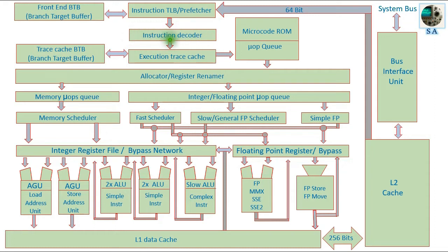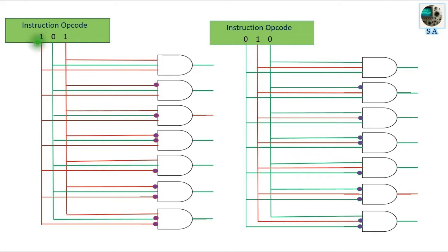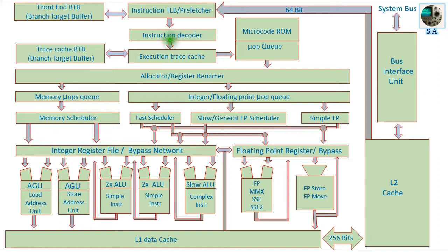The interesting thing about decoding instructions: the zeros and ones of the instruction opcode itself represent a unique control signal for every instruction opcode, each having different bit patterns. So after decoding the opcode content, these signals directly drive the combinational logic, which is triggered by the clock signal with a repetitive sequence of pulses from the internal timing generator to produce all the control signals.